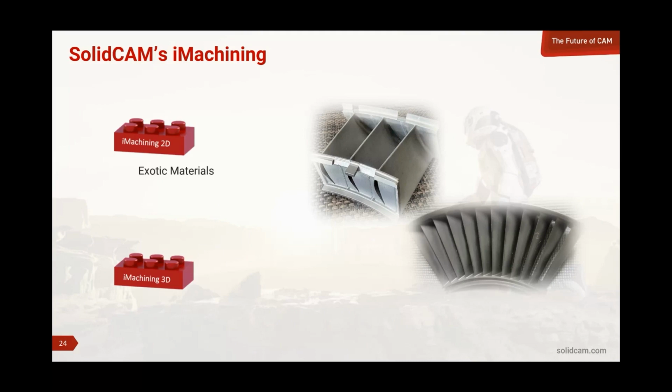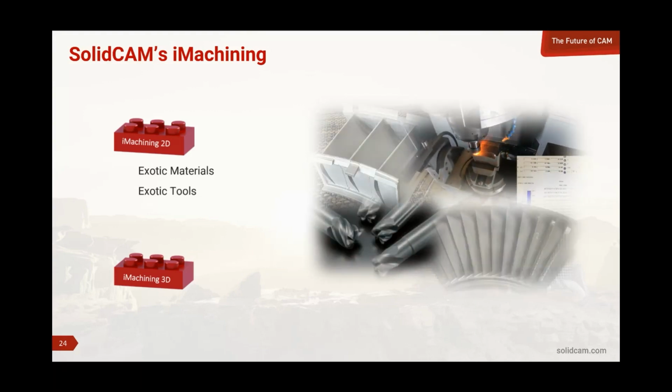Okay, this is jet engine hot section material. This is some of the toughest material you will see in the world. It's designed to have an extreme, what they call creep rupture strength, where it can stand up to extreme pressure at highly elevated temperatures like the internals of a jet engine. Okay. In doing this, we're actually doing this cut. This is a material called Rene 65. This is a GE proprietary material that is very, very difficult to cut.